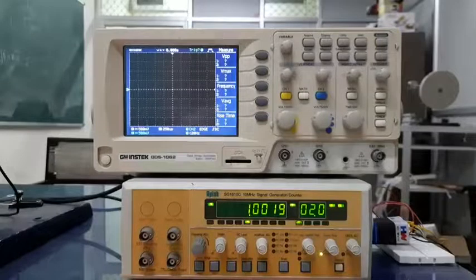Now, when you want to see the signal, your oscilloscope is a measurement device, just like your digital multimeter. It's primarily used to analyze AC signals, but it can also be used to analyze DC signals. So all the measurements that one could do with a digital multimeter in terms of voltage measurements can be performed using a digital oscilloscope also. It's also sometimes called a DSO, right?